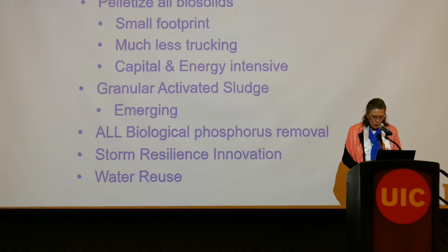I mentioned the Delano Sugar redevelopment, so 0.4 MGD from 5 buildings on 11 acres, return on investment of 14 years. These are the business practices that we need to change our local incentives to. We need to incentivize the work we want to see. This also reduces potable use demand by 200,000 gallons per day. It provides a drought-resistant water supply for those buildings for non-potable purposes. It reduces flow to stormwater sewers and wastewater facilities, and thus the incidence of combined sewer overflows.